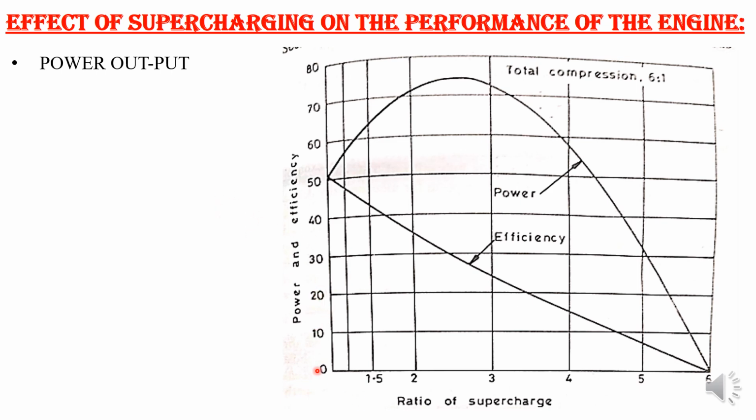So as the ratio of supercharge increases, what will happen? Look over here, the power will increase up to a certain limit of the ratio of supercharge, then it will decrease. That means only up to a certain limit can we use the supercharger at maximum. After that we can't use it.